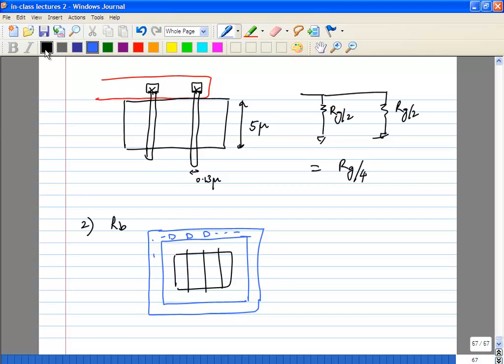Let's say you have an RB. The noise from this is 4kT RB delta F. The noise at the transistor output is 4kT RB gmbs squared delta F. So we will stop with that for LNAs.